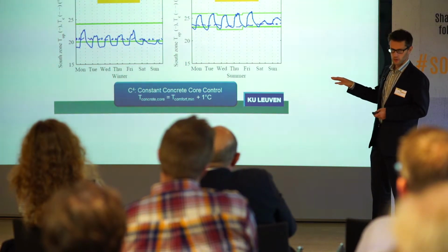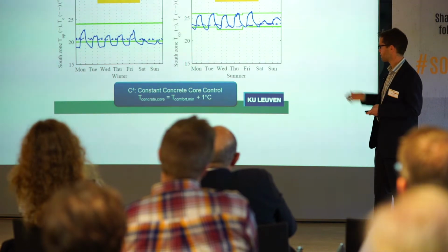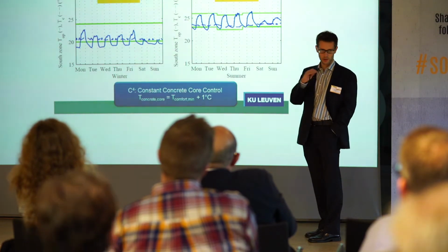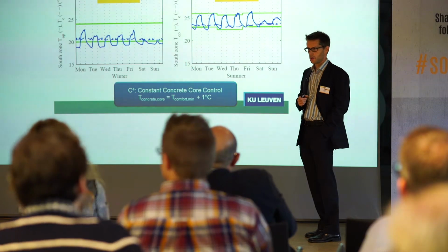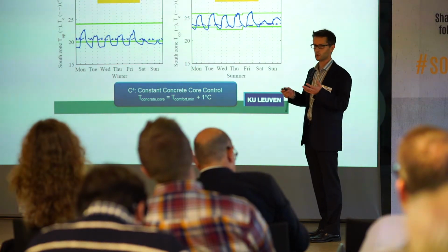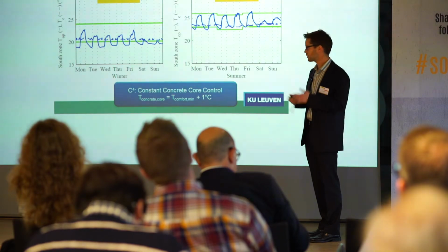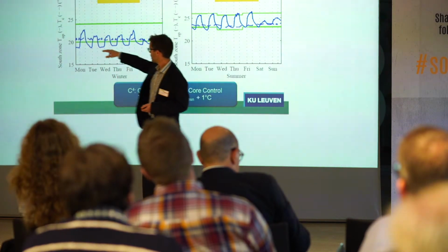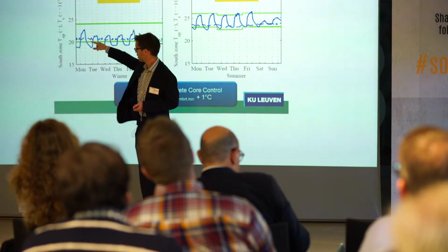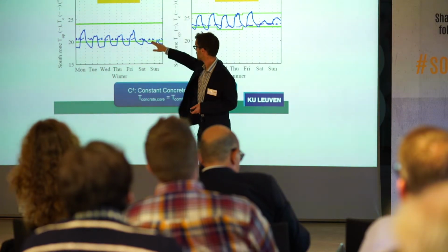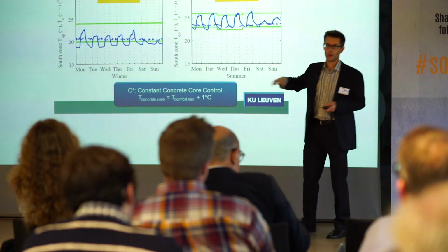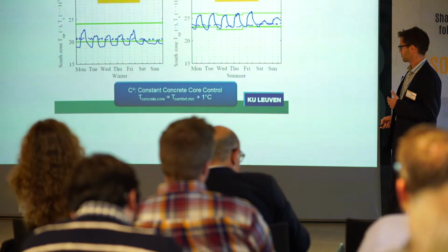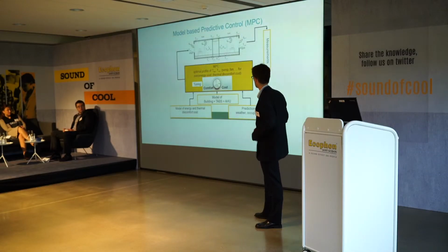If you look at the rule-based control, we did a lot of variations, analysis of parameters, and actually we came up with the best result: just keep the taps at a constant temperature. You can do other things, but there will always be other situations where that measure is not good. So the best thing is just keep it at a constant temperature, at which one, well, we saw approximately 1 degree above the lower comfort limit. Both in heating and in cooling was the same result. So as a guideline, we had that as conclusion, okay, just keep it constant. It's overall, in a whole year, the best solution.